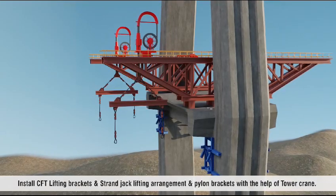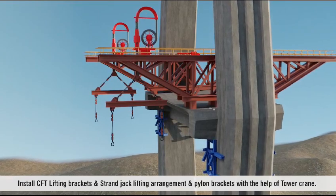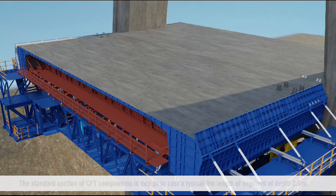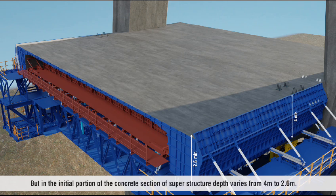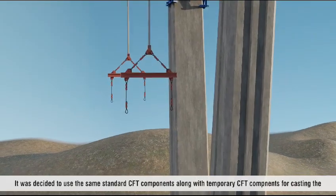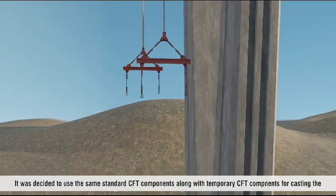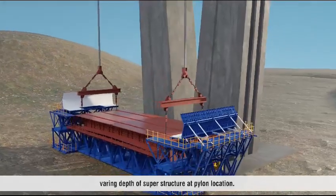Install CFT lifting brackets and strand jack lifting arrangement and pylon brackets with the help of tower crane. The standard section of CFT components is designed to cast a typical 9 meters length of segment of depth 2.6 meters. But in the initial portion of the concrete section of superstructure, depth varies from 4 meters to 2.6 meters. It was decided to use the same standard CFT components along with temporary CFT components for casting the varying depth of superstructure at pylon location.